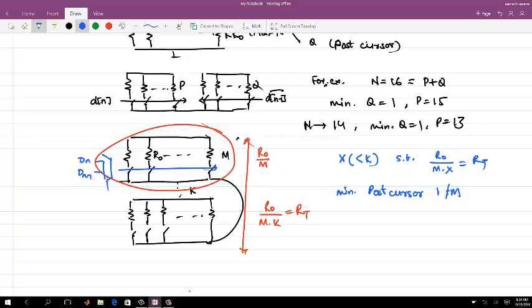Here I have shown you a uniformly segmented version. What is normally done is you make this particular cell binary weighted and select between dn and dn minus 1, and then you have these cells copied to select depending on the process variation.